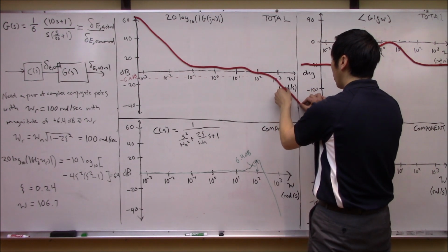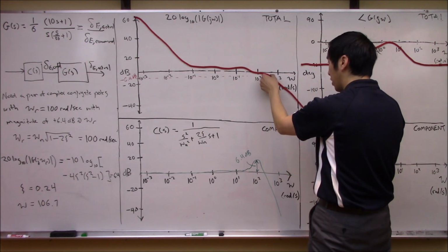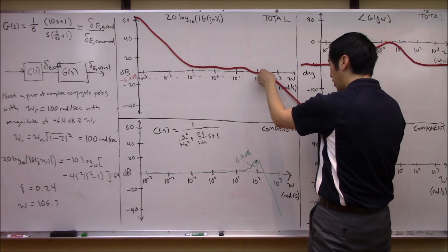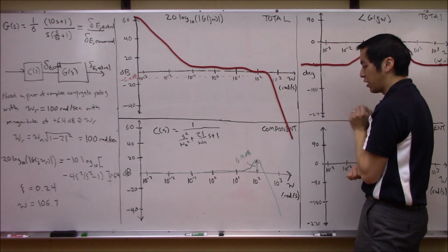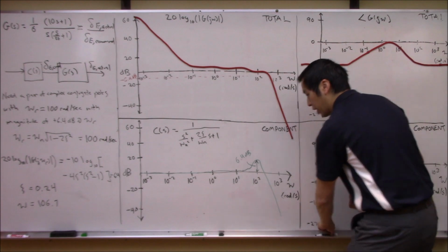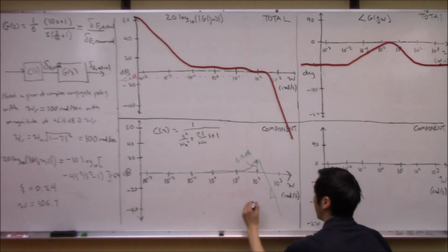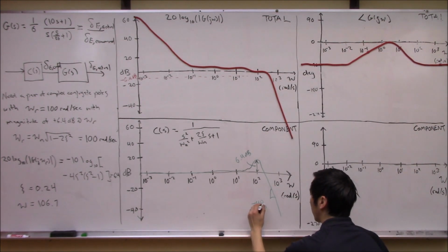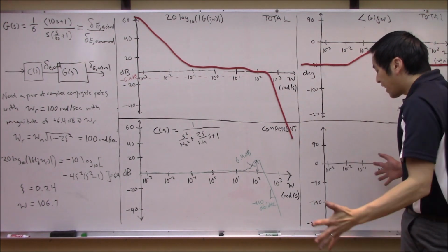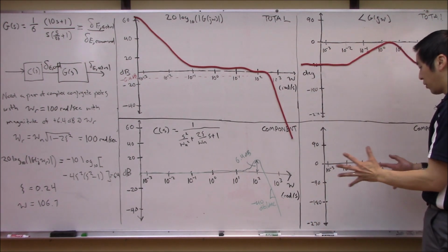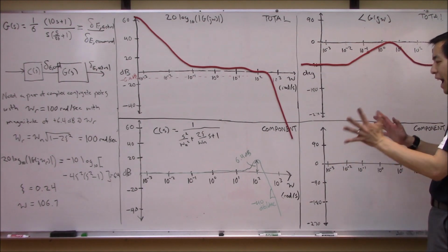So we'll shift the whole thing up by 0, and actually, then it's going to, unfortunately, the price you pay for that is this slope is going to get steeper by 40 decibels per decade here, right? Because now this slope here is negative 40 decibels per decade, right? And I guess if we want to make this completely accurate, maybe what we should do is we should also talk about the phase.